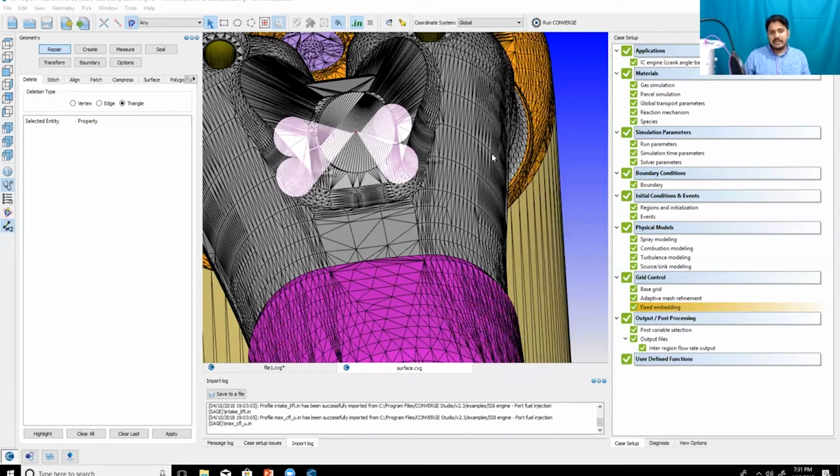Nirav Vyas, sir, any books or online resources to learn this software from basics? Maintaining the same base grid, yes. If you have a lot of computing power, Nitin, modifying the base grid is an excellent strategy. The problem is, if you're using adaptive mesh refinement with a different size base grid, your seed solution is going to change. As you know, before adaptive mesh refinement kicks in, it takes the SGS values, which are second derivatives, from the base grid. So modifying the base grid is going to affect that SGS field that you have for AMR. So your AMR is going to be different.